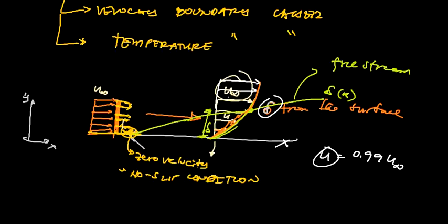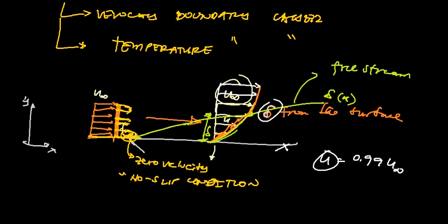The ratio of the two is what we call the kinematic viscosity, nu. We have already encountered this term, and the kinematic viscosity decides how far the presence of the plate will be felt by our fluid stream in terms of the velocity gradient. If our kinematic viscosity is large, then we can expect a greater boundary layer thickness. So that is the relationship of those properties.